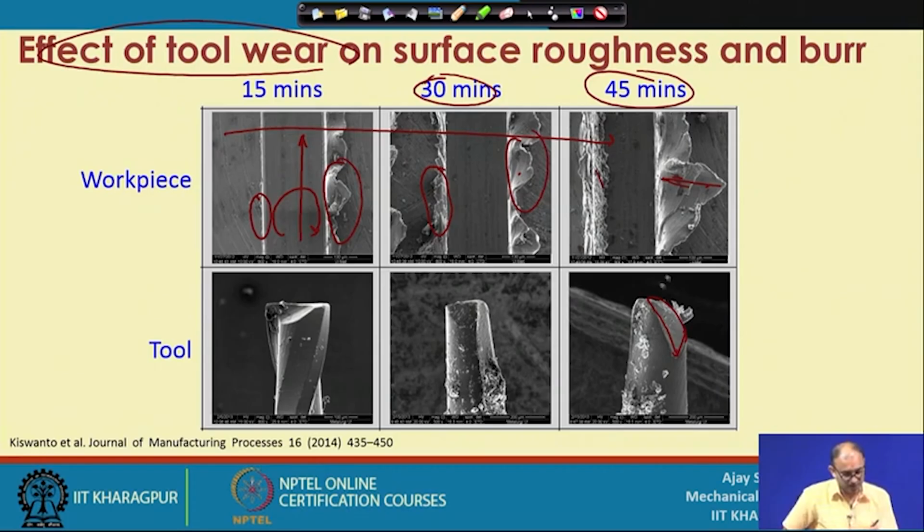So, now getting a surface finish is also important, because if you see in this location, the surface is very fine, and now here you are getting some type of problems. So, these are the residual material which are staying, and then you are getting marks also. So, these are the marks, and when you end up using this worn tool further, then your roughness is also very high, correct.